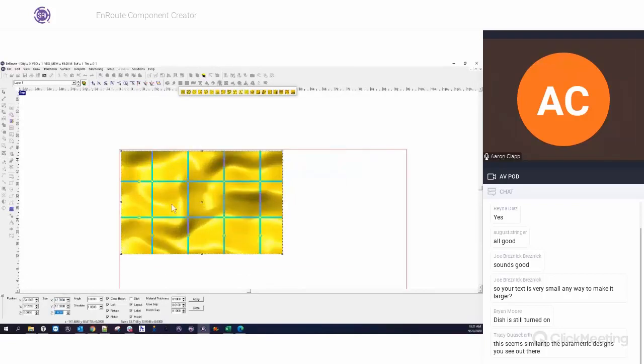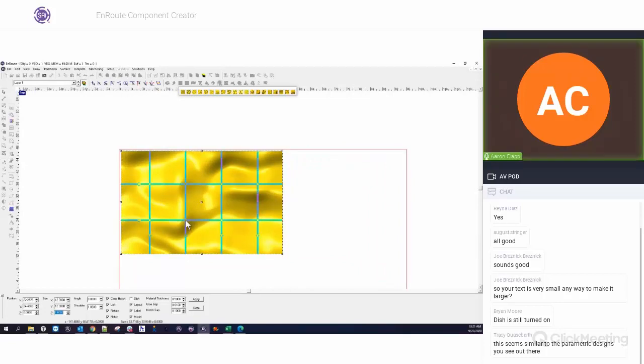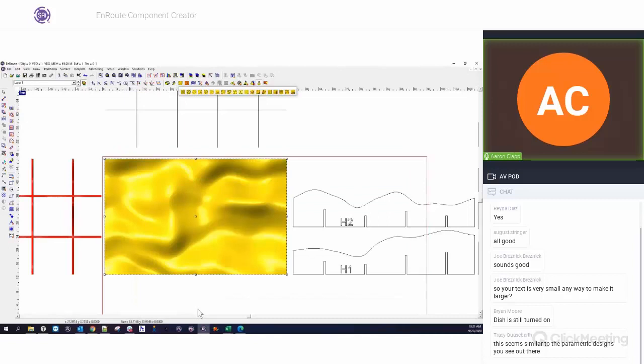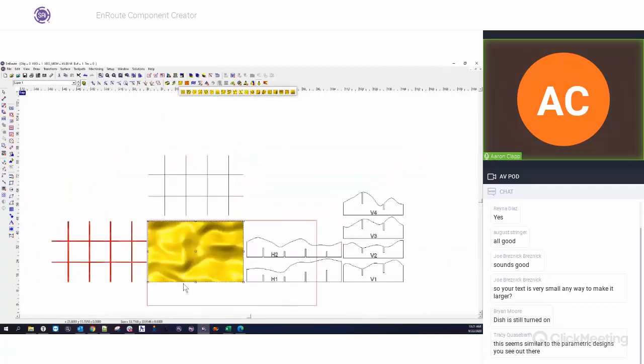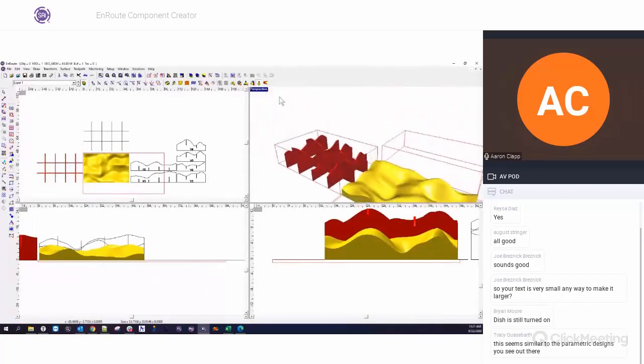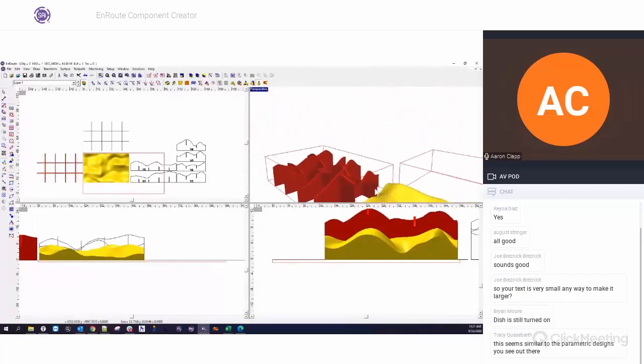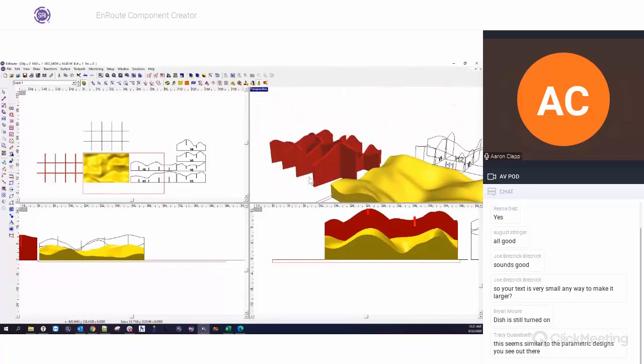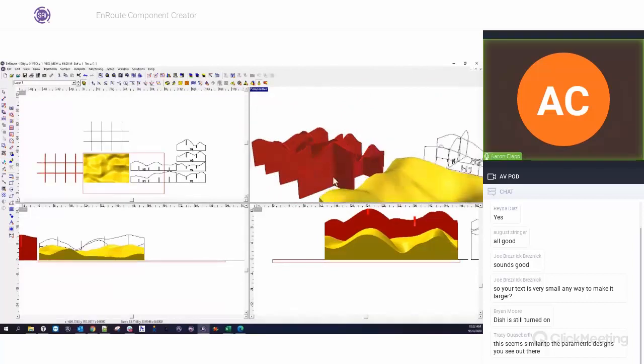That way I get a little bit better of a pattern. I don't want too many panels in here. Apply. Go back to our perspective view here. And so that time I put in a return height of 5 inches, so it gave me a lot taller design, but it still follows this same shape.